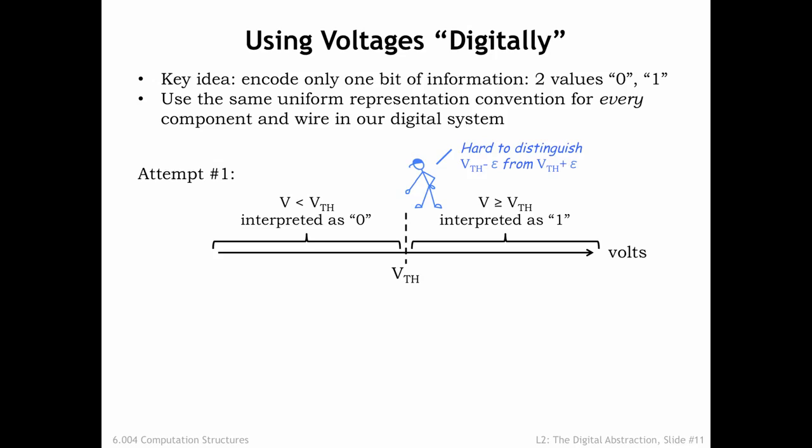The problematic part of this definition is the difficulty in interpreting voltages near the threshold. Given the numeric value for a particular voltage, it's easy to apply the rules and come up with a corresponding digital value. But determining the correct numeric value accurately gets more time-consuming and expensive as the voltage gets closer and closer to the threshold. The circuits involved would have to be made of precision components and run in precisely controlled physical environments. Hard to accomplish when we consider the multitude of environments and the modest cost expectations for the systems we want to build. So, although this definition has an appealing mathematical simplicity, it's not workable on practical grounds. This one gets a big red X.